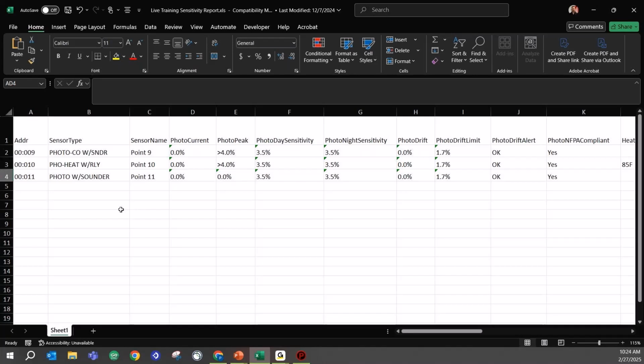I wanted all of the peak values wiped off of all of those detectors. As they did their inspection, I would expect to see new peak values getting written in for smoke detectors, heat detectors, etc. The reason why I like this is this shows that I actually introduced smoke into the chamber of that smoke detector, or actually applied heat to the heat detector.